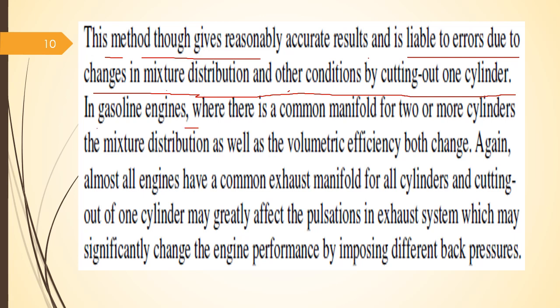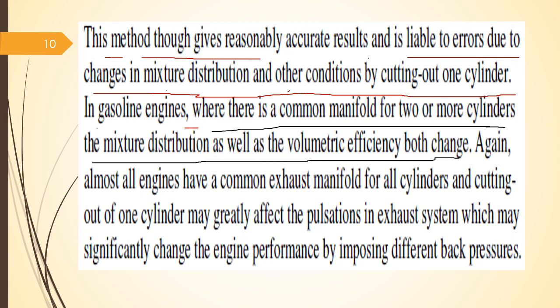If we talk about a petrol engine, there is a common manifold for two or more cylinders. In a multi-cylinder engine, if we cut one cylinder, the way in which the mixture is distributed and the volumetric efficiency both will vary.